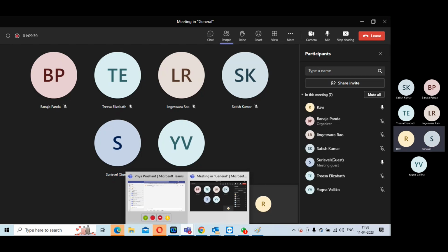I don't have congestion, placement timing is meeting, but post CTS timing is getting screwed up because skew is more because that block is sitting there; at placement, the clock is ideal. To that extent your floor plan can change. You get the point?